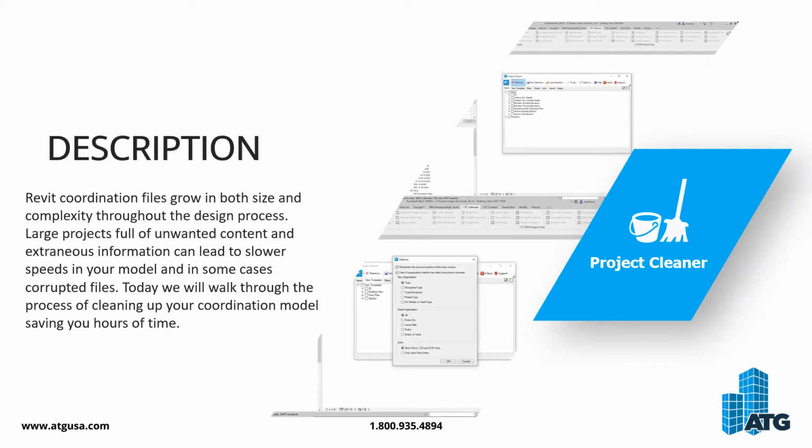Or maybe we have a coordination model, right? So we're receiving a coordination model. I come from a structural design background. I receive an architectural model, and I want to link that into my Revit model as an underlay, right? So I can start my design basis. And they have a large file size. They have more renderings, more views than probably what I would have. And I need to clean all of that out to reduce that file size.